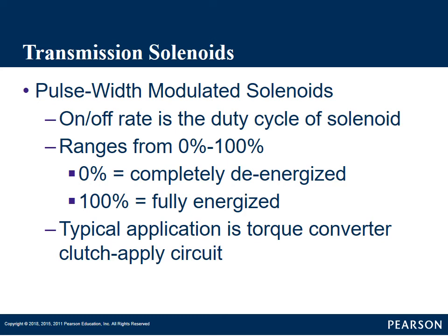Before I go into pulse width modulated solenoids, and we'll get into this a little more when we talk about electronics and diagnosing them on transmissions, here's how to think of solenoids in a hydraulically controlled system. We have a governor and a throttle pressure, and they've got to work against each other to get the transmission to move.